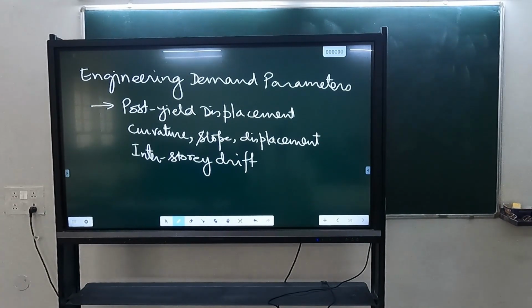But in case of a frame structure, the frame, RCC or steel frame, may be structural, and infills may be treated as non-structural. But whether we treat them as structural or non-structural, in reality, those are affecting the load distribution in our structure. So that we have to recognize. Even if we declare them non-structural, we can't ignore them while analyzing our structure. We have to consider them. That's the difference between other non-structural elements and masonry infills, because those are significant, even larger than that of the frame, in strength and stiffness. So we can't ignore them.